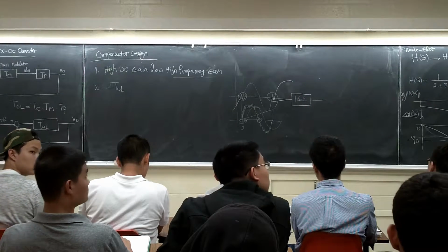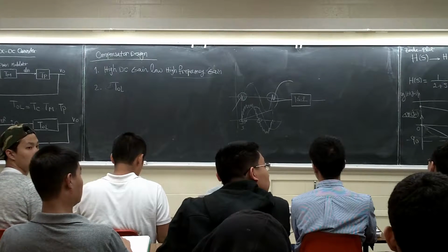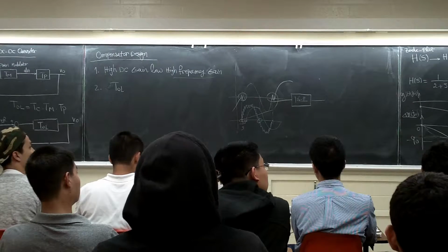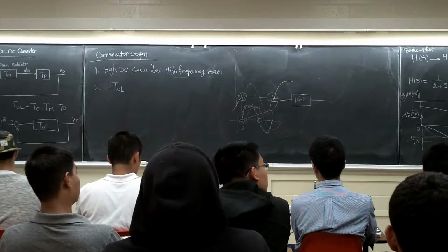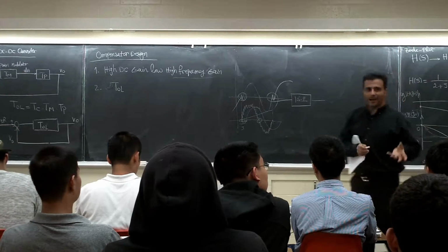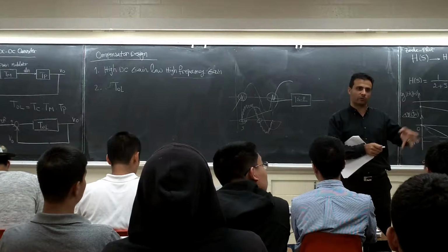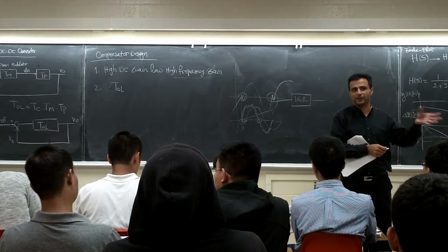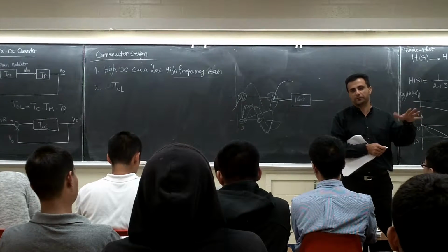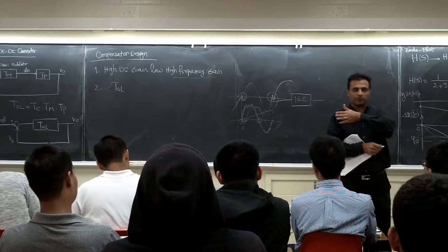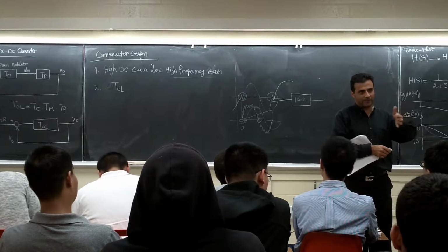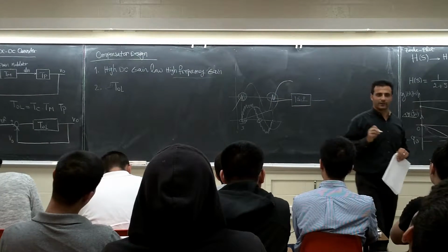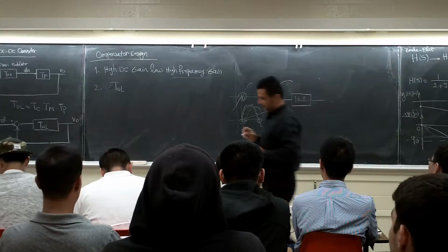Can't you pick an inductor and capacitor so the phases cancel? You cannot. Believe me, we have spent a lot of time on it. We tried a lot to do that, but this is dynamic, it's not fixed. If it was one value, you're right, you'd go find that one and compensate for it. But for different current, different voltage, it is different. Voltage is fixed, fortunately, at 120 volts. But the load is variable, and that is going to affect this. We spent lots of time on this, and now it's much better than what it was before, but it still is not what you want.